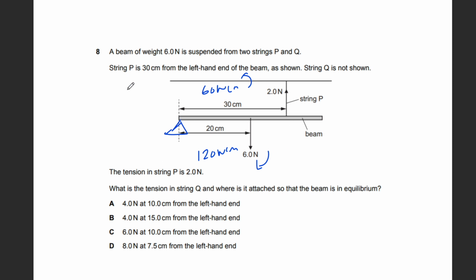So we need an anti-clockwise moment of 60 Newton centimeter. So we just multiply those values, right? See if it gives us 60. This is 40, no, this is 60, this could be right. This is also 60. Like 8 into 7.5 is also 60.